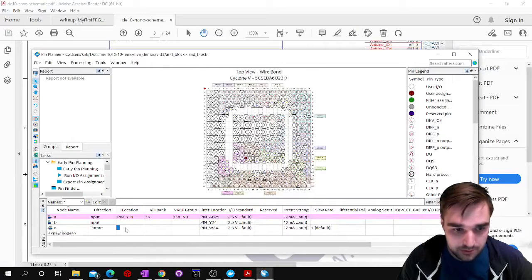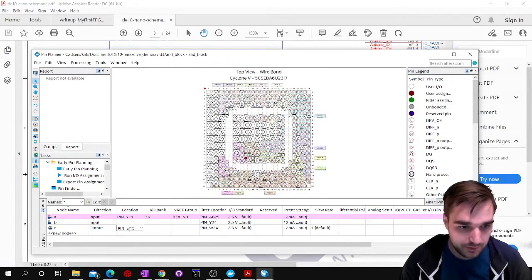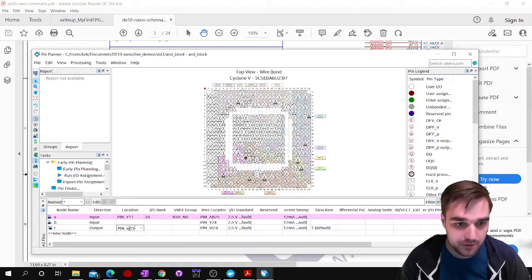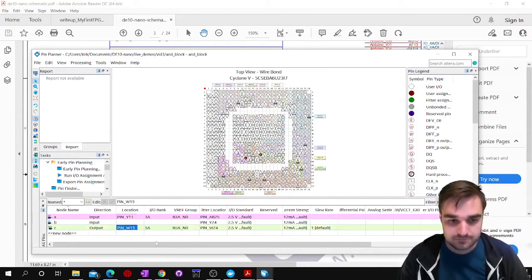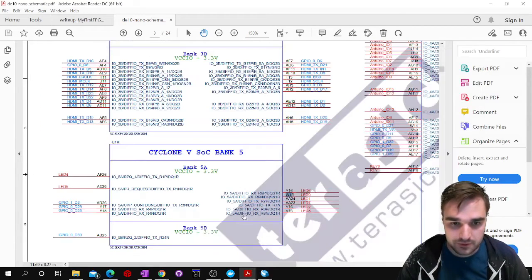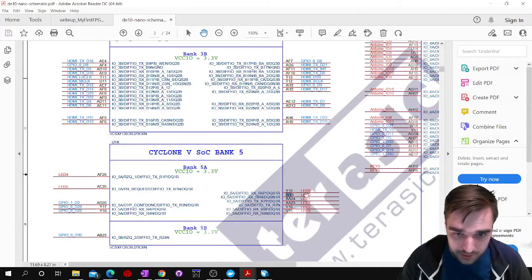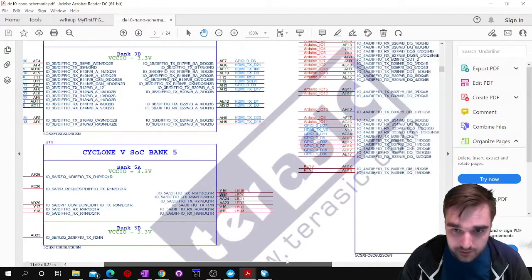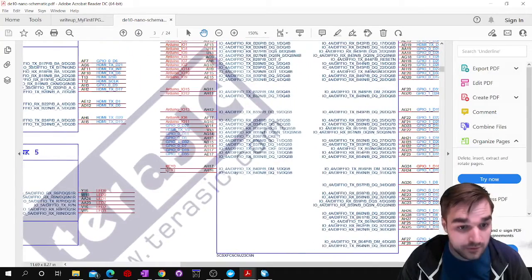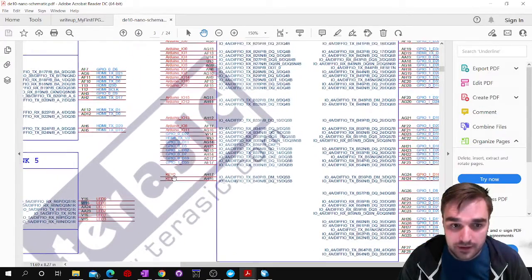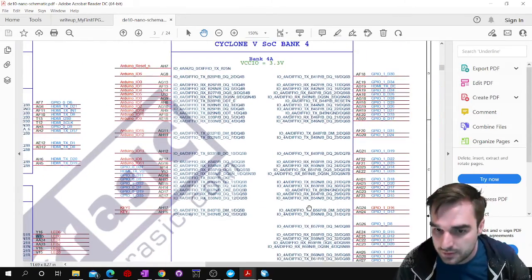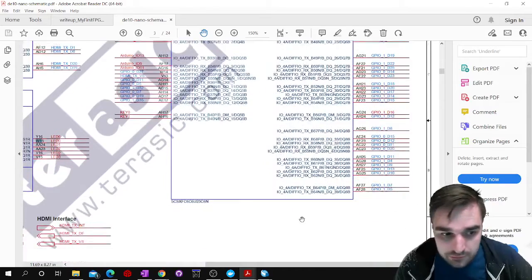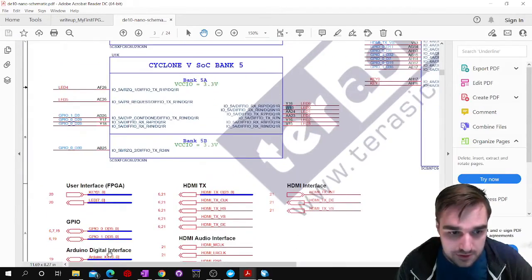So on my output, I'm going to type in W15 and it types in the pin for me automatically. I did not type pin underscore. I just put W15, push enter, and it's done. Great. So the output is now done. We still needed the input, so we have to find where the switches are. So GPIO, LEDs, no, we don't want GPIO. Key 0, key 1, we could use those. I just know from memory that key 0, key 1 are the push buttons. They're tiny, tiny push buttons. But no, what we're after is the switches, and I'm not seeing it on this page.